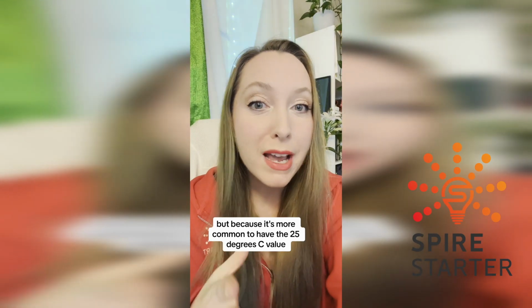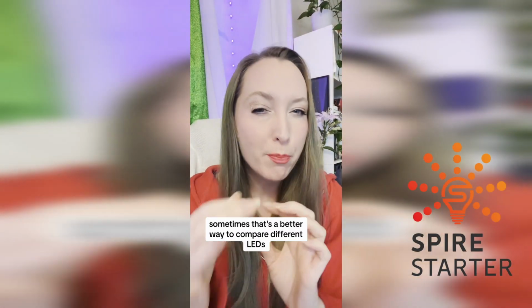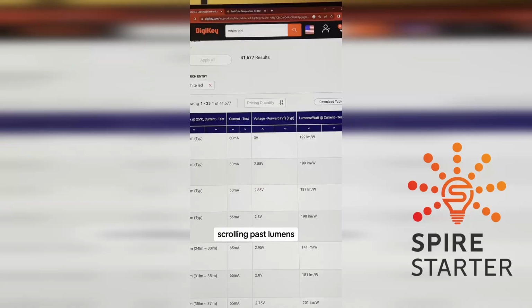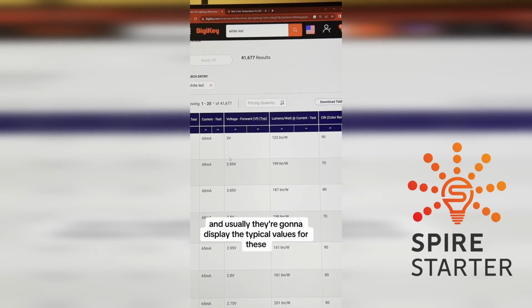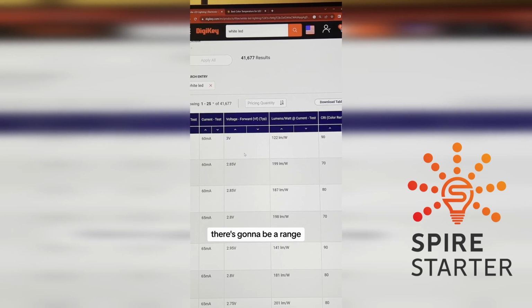But because it's more common to have the 25 degrees C value for how many lumens are coming out, sometimes that's a better way to compare different LEDs to see which one is most efficient. Scrolling past lumens, then we get to current and forward voltage, and usually they're going to display the typical values for these, even though, especially with forward voltage, there's going to be a range.